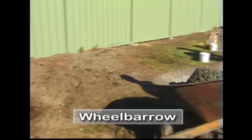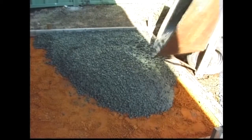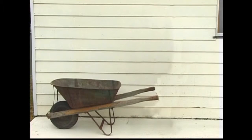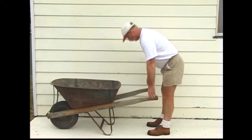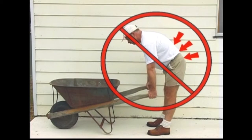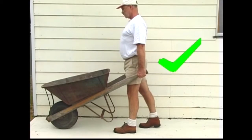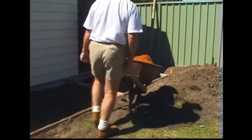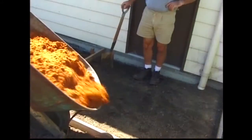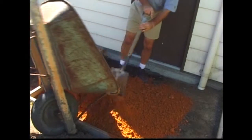Wheelbarrows are the most common way to carry materials on building sites. The bulk of the load should be placed centrally and forward in the tray, close to the wheel. Incorrect lifting practices can cause back injury. To lift correctly, the operator uses the legs and keeps the back straight. Tipping should be controlled and gradual, not a rapid discharge of the load that catapults the barrow forward.